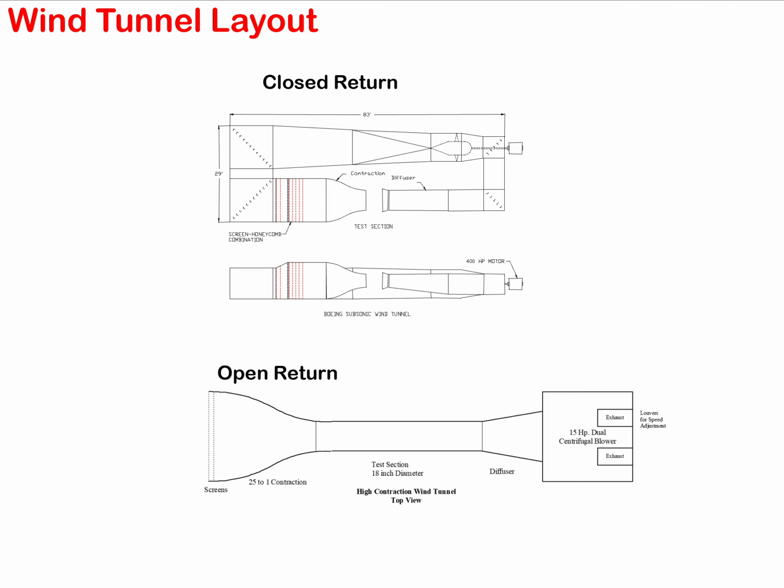The closed return wind tunnel essentially means that it is circulating the gas inside. The reason for a closed return wind tunnel is interest in doing simulation or analysis for special atmospheric conditions. For example, if you want to do a wind tunnel test on a device that is supposed to move on Mars, you can't really run a wind tunnel test in an open return wind tunnel. You have to use a closed return wind tunnel that is sealed from outside, so you can simulate the Mars's